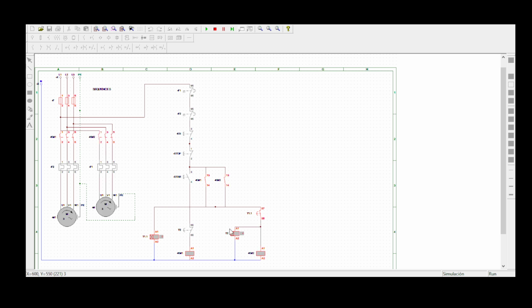They've energized, and immediately when they energize, remember timer 2 is also counting. We want this coil to de-energize after 10 seconds. So after 10 seconds this should stop. Your motor 1 should stop operating. Let's see, it should stop any time now, and that's it. It has stopped rotating.